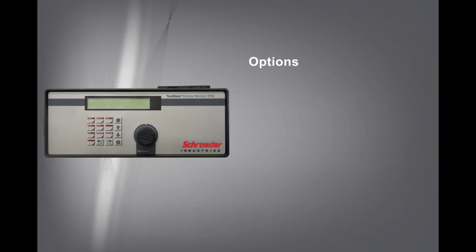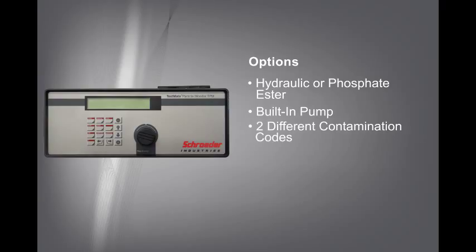The TPM can handle either hydraulic or phosphate ester fluids. The TPM comes with or without a built-in pump. Please note, you will need the built-in pump to do bottle sampling. Cleanliness can be displayed in 2 different contamination codes. You can choose to display the cleanliness in ISO and NAS or ISO and SAE.